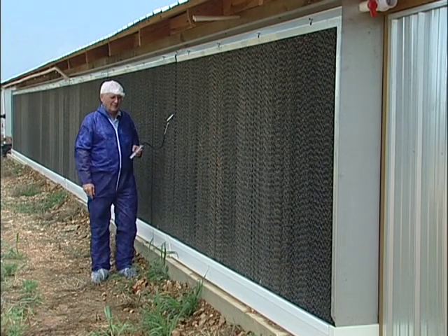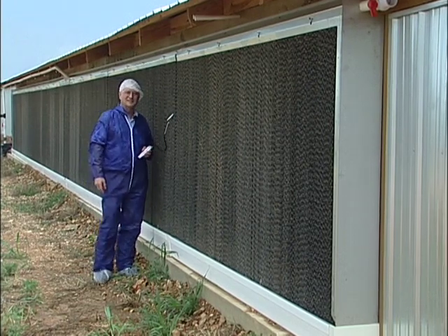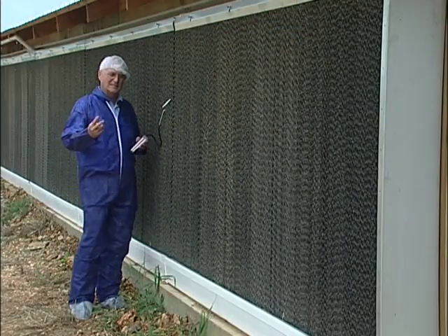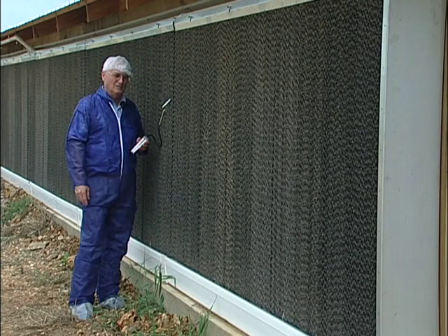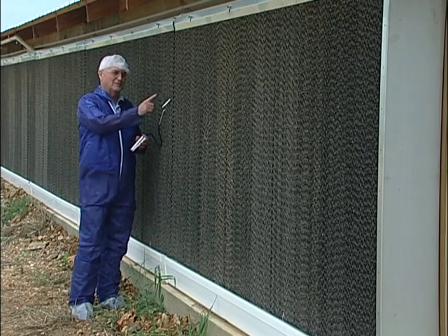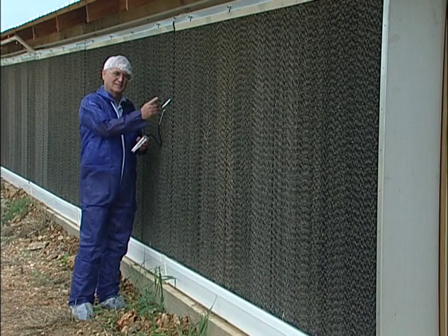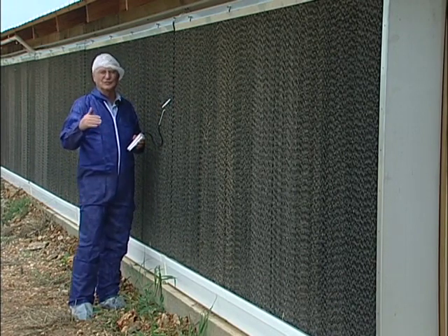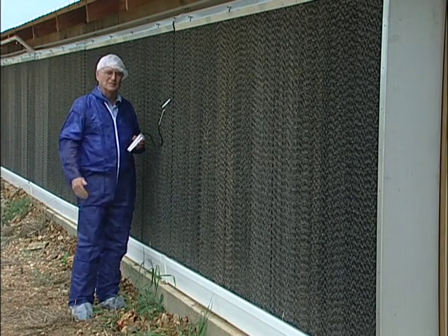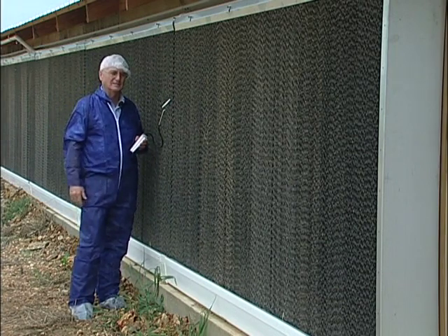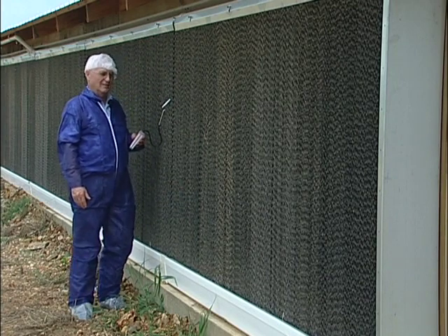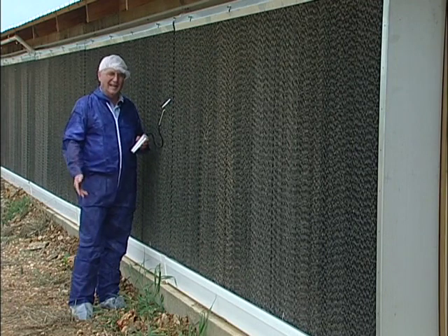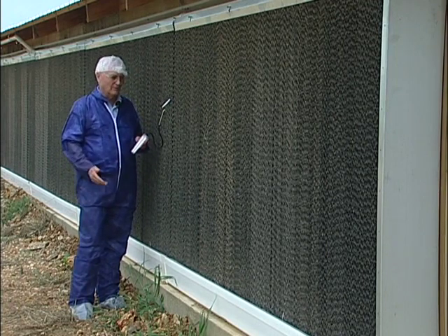All right, what we're going to talk about now is the installation and sizing of the evaporative cool pad. There's basically two pads that we use, and one is a 45-15, which you see on this particular house. That's by far the best pad to use when you're subject to low humidities, from mid-range to low humidities. And then there's a 30-30 pad that's available, and that's normally the best selection when you're in high humid areas because of the way the water flows.